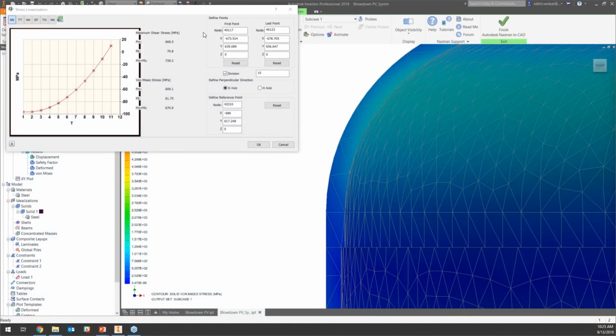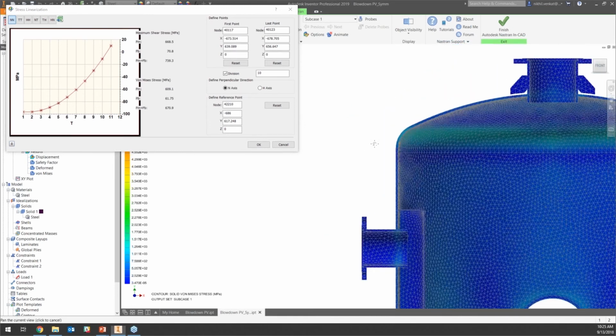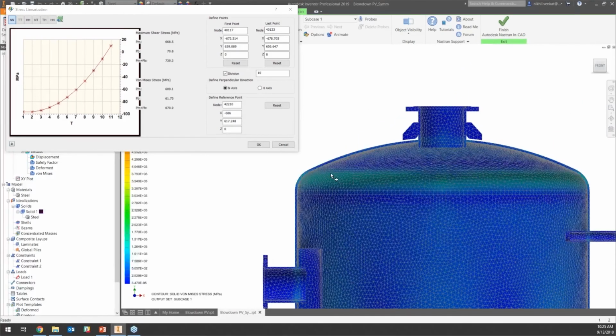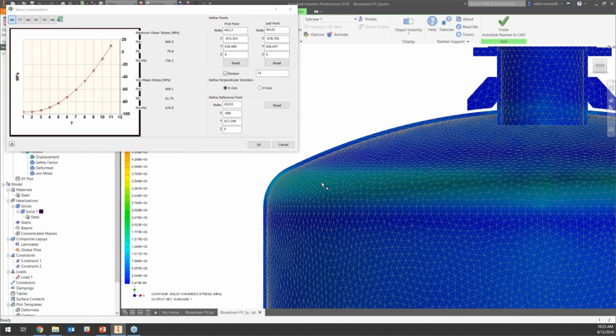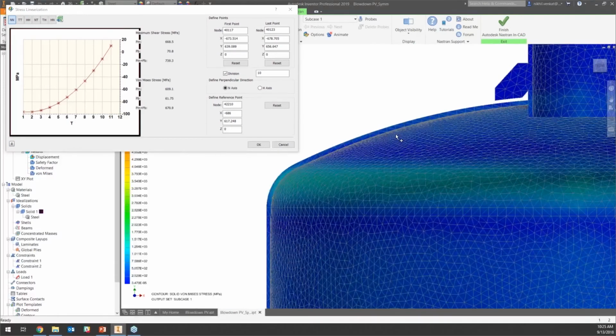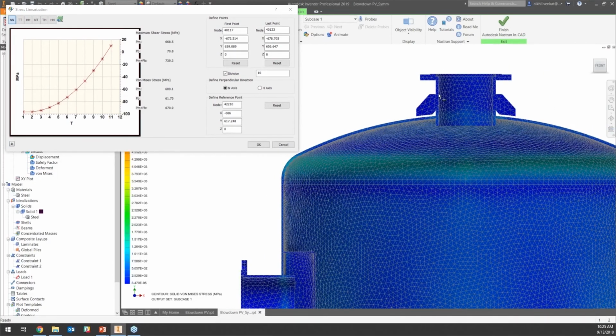Now, you could say, well, I have seen membrane stresses in Nastran In-CAD before. I can use shell elements and get a membrane stress, and that would make total sense. You can use a shell element almost through the midplane of this, and assign a thickness to that, and go from there. A couple of issues with that. One being, potentially, you could have certain components that cannot be shelled, or that can be shelled but don't necessarily make sense to be shelled.